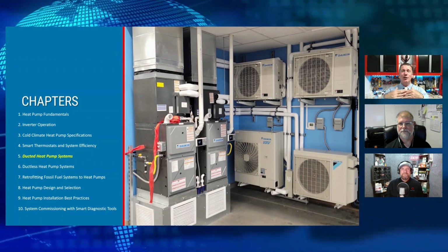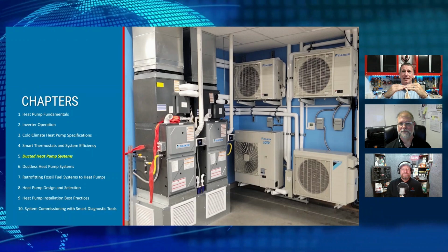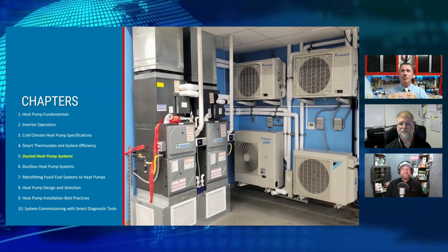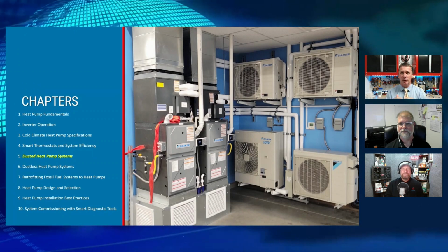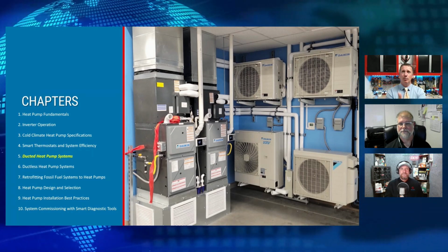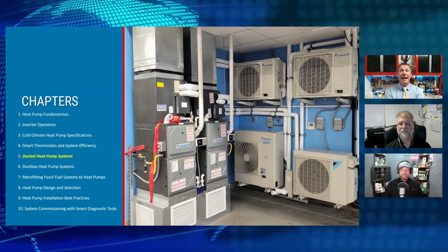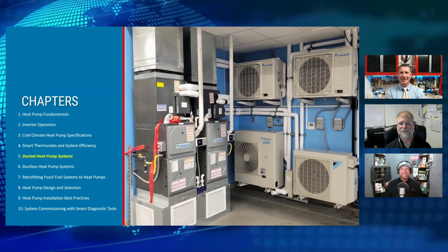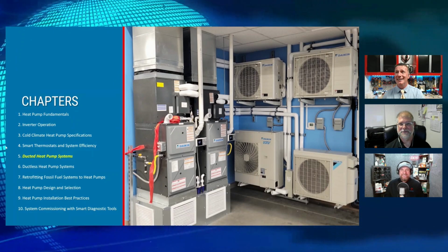Well, if I start reducing the airflow across my indoor unit because of my excess static pressure, it changes my superheat, which is going to change the modulation of my outdoor unit. It's actually going to affect my capacity in correlation with airflow. And so never in our industry have we ever been to the point where we have to focus on airflow for maximum efficiency and capacity of our outdoor units. I know I went down my tangent, but I absolutely love getting on that topic.